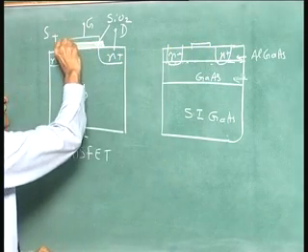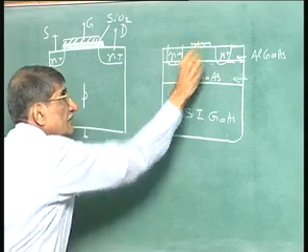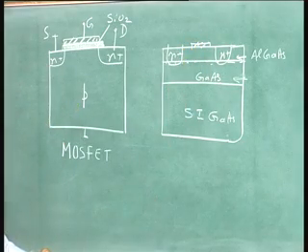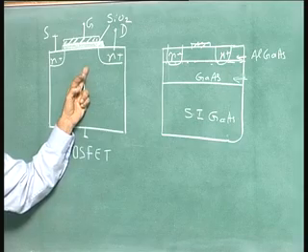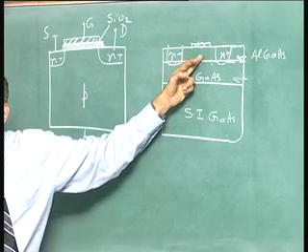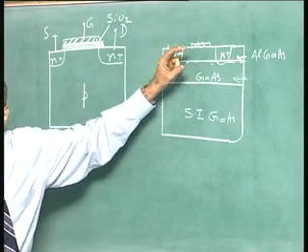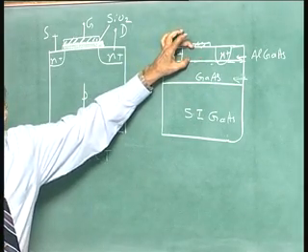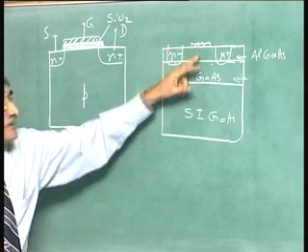So, I can call this the gate; in the case of MOSFET, this is a gate, and in this case too. The difference is that MOSFET is metal oxide semiconductor, while this is a metal semiconductor contact, a Schottky barrier, but you ensure that the thickness, doping, etc. is such that the built-in potential itself will deplete the whole thing. So, you do not want this to conduct.